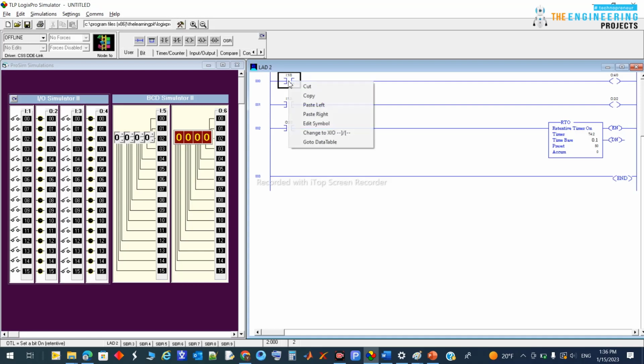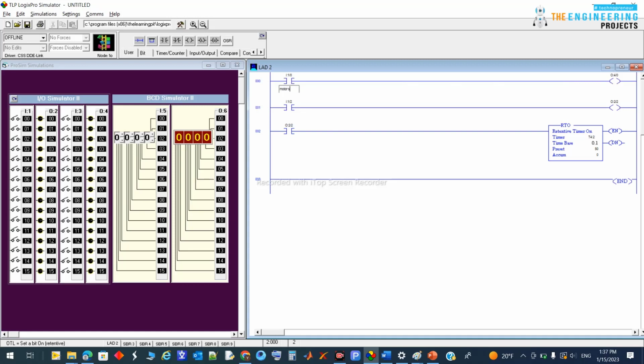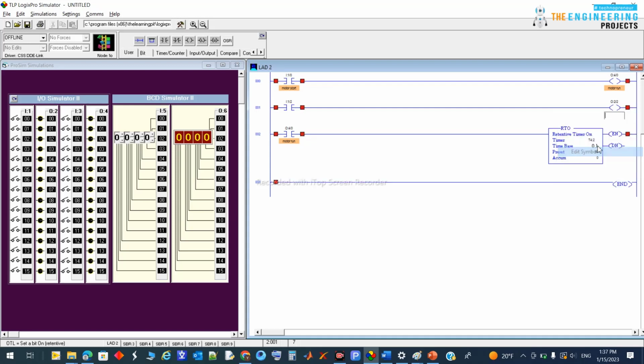So this is the start for your motor here, motor start, okay. And this one is motor on, okay. It will be motor run, okay. And if I have the motor run here, because this is the output, I put the output here. So every single moment the motor or the pump or the heater or the machine itself is operating, the retentive timer will count until reaching the time we designed the machine to enable one alarm, showing you that it is now time to make the maintenance. So this will be the alarm maintenance.